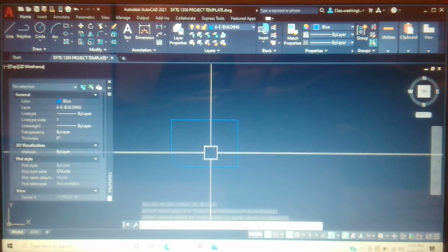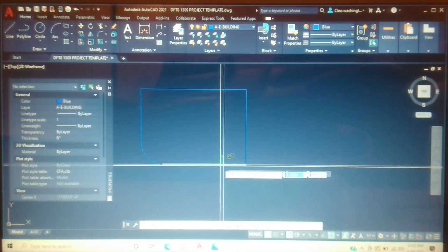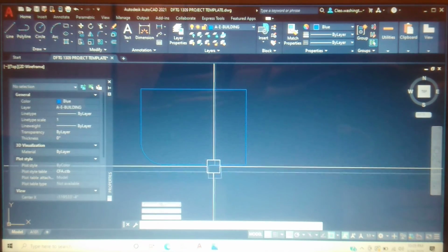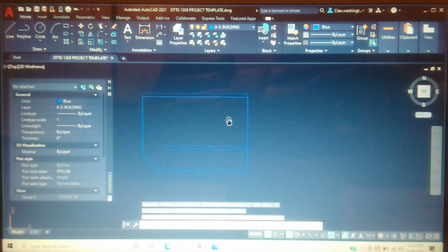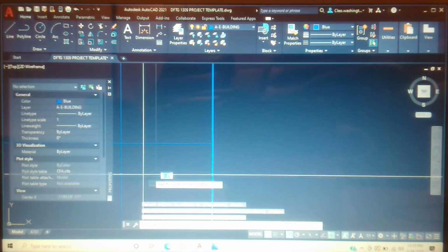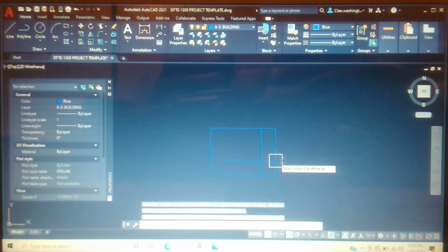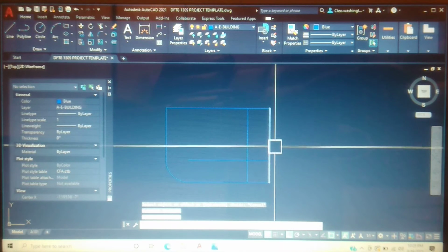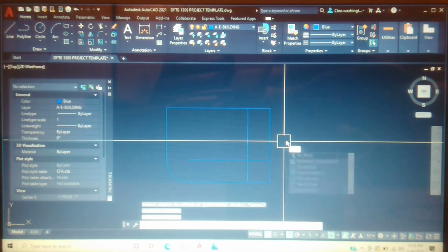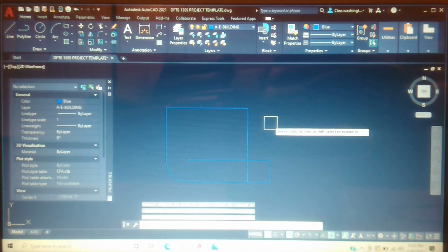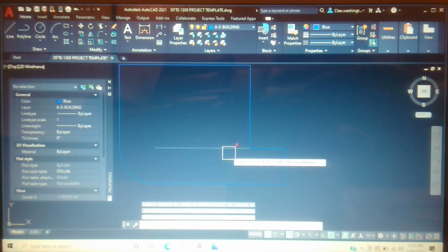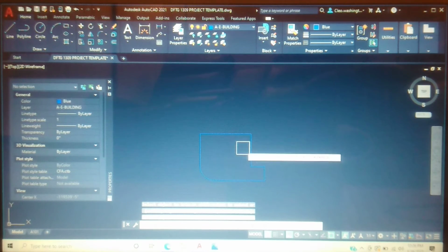Okay? So now next thing, let's take this line right here and offset it 3 foot. Okay, and let's take this line and offset it 3 foot. Good. Offset it to the west, 3 foot, the plan west, 3 foot. And let's go ahead and clean this guy up. So you activate the trim command, you type in TR, space bar once, space bar twice. Let's go ahead and define the lines like we did in the past couple of weeks. Okay, so there you have your part.